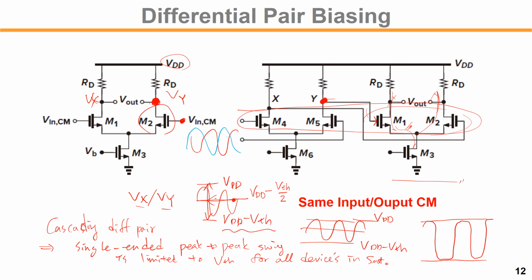Okay, so if you don't want to satisfy this, sometimes, as I explained, for clock buffering, you may allow the input device in triode region, so that the input device just works as a switch, a digital switch, right? Like this. In triode. Okay.